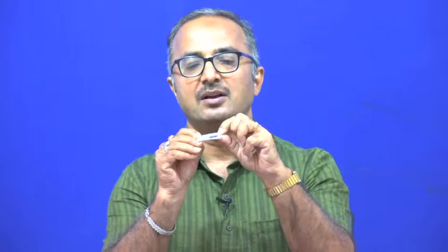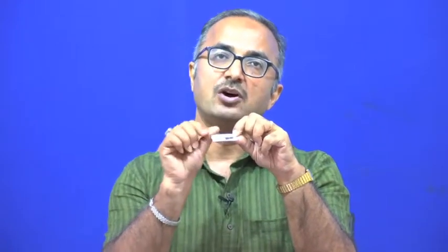So this is how a pressure transducer looks, and here I show you the strain gauges which are very small. Their strips are there, and these strips are pasted wherever we want to measure the pressure drops, and these strips will change the resistance, and the resistance is measured appropriately to get the pressure drops. Thank you.